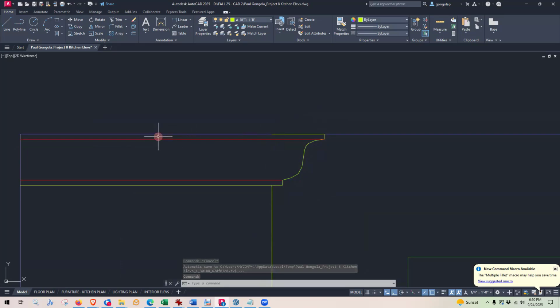When I'm plotting this out, this is going to be a heavy line and then it's going to get lighter and then heavier. And I don't want that. I want this to be continuously heavy. So I can either change the block to remove this top piece here, and that probably is what I'm going to do. But I just want to show you another way, and that is to change the order of the lines and to bring this line to the front.